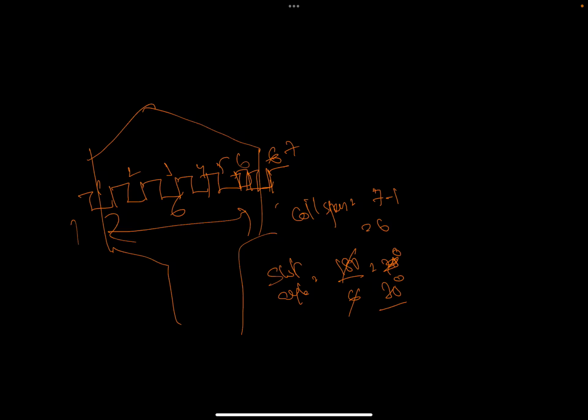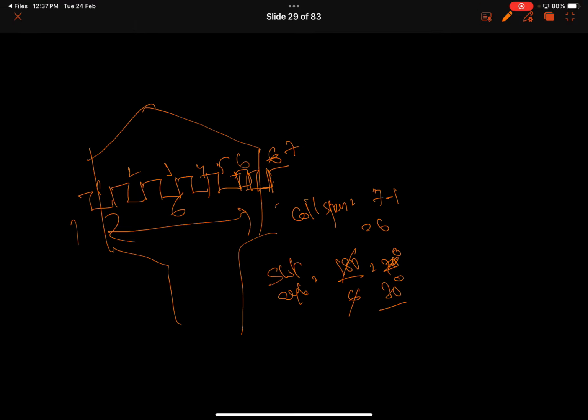Now what I am trying to do here, listen, instead of placing at the 7th slot, I am keeping the winding in the 6th slot. See here, I am keeping the winding in the 6th slot. So this is short pitched winding.